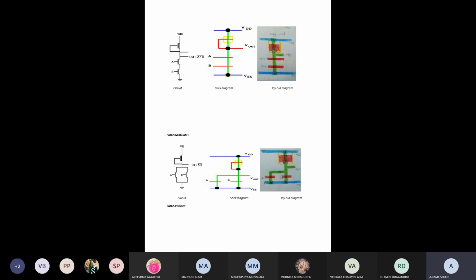So in this overall diagram we have NMOS transistors made up of N diffusion. So N diffusion will be marked or represented with green color. So from top to bottom, we draw a green color line. Here we are using a different mode of transistor, that is depletion mode and enhancement mode transistor. For depletion mode transistor, we have to overwrite that green color with a red color, that means polysilicon, to work like a transistor.